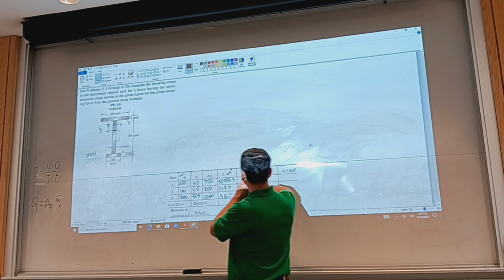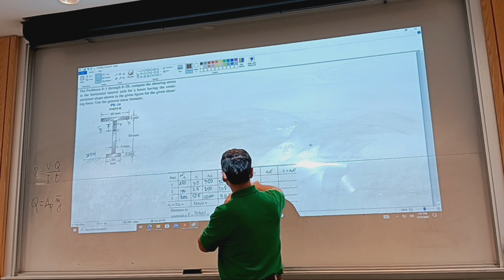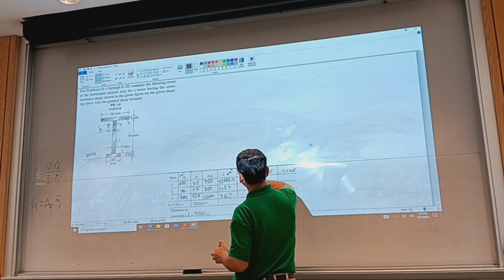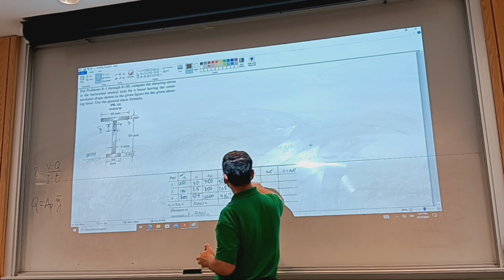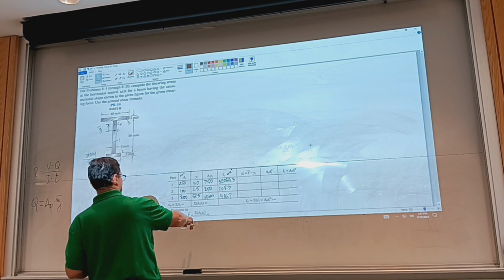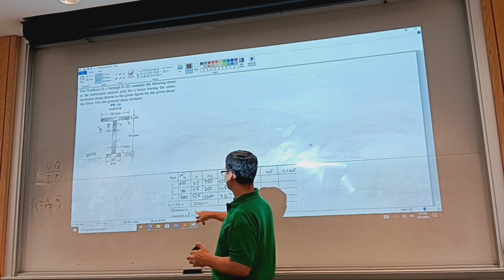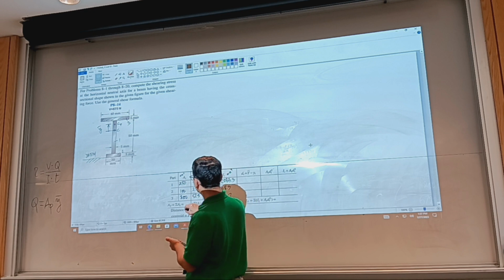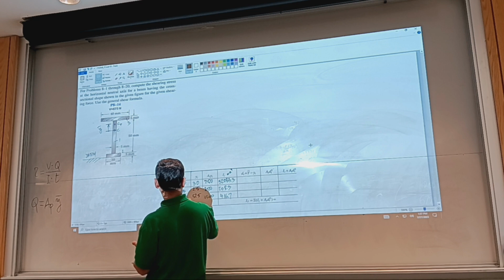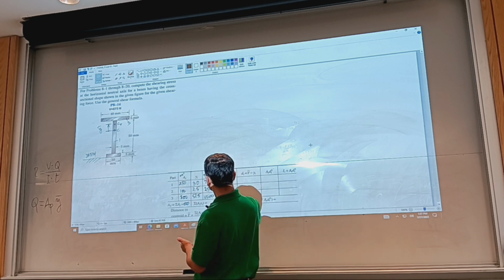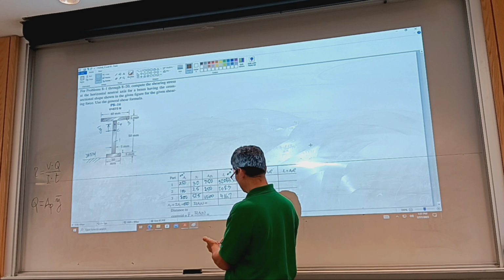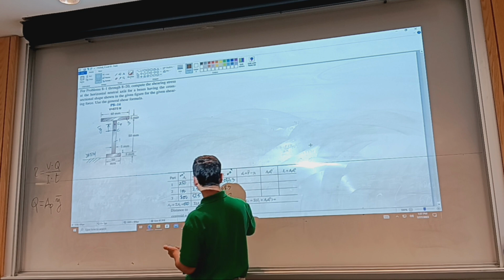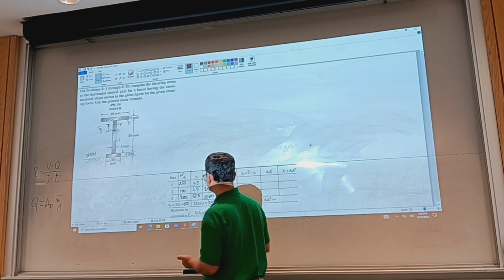Okay, so next step is to extract from the figure the distances from the, well, I need to evaluate the centroid of the piece first. So sum of areas, it will be 250, 350, 550, like right here. And then sum of, so I have 750 plus 250, it's 1,000. And add it to, so it'll be 12500. Okay, so I can calculate the centroid.